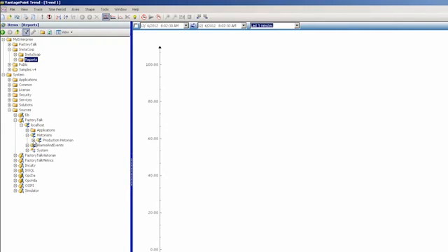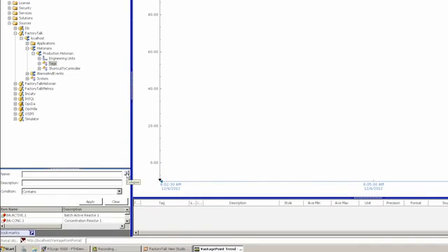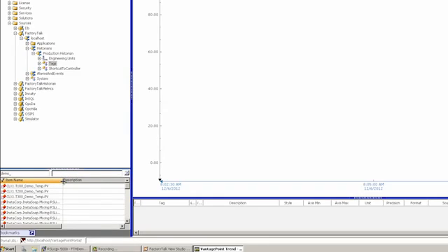Through FactoryTalk, we can find our production historian and choose to display all of the configured tags. Once the configured tags are displayed, we want to use the built-in tag filter to quickly find the specific tags created for this demo. This shows us 3 configured tank temperature process variables.